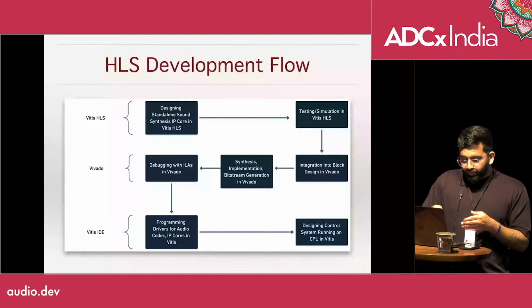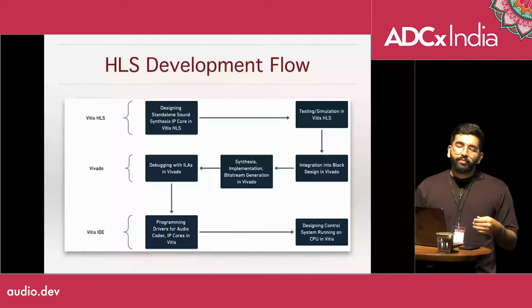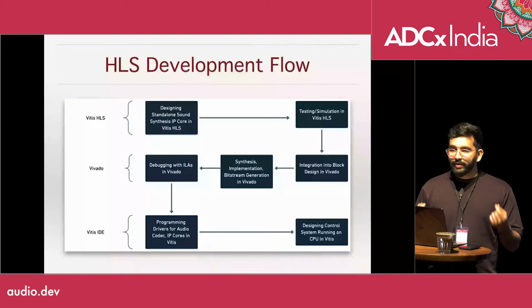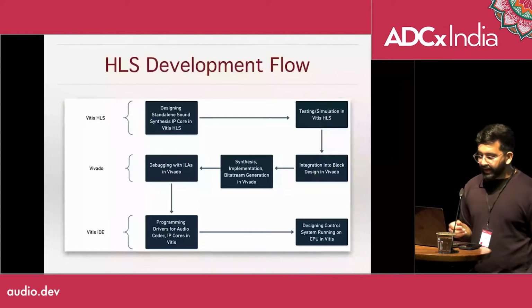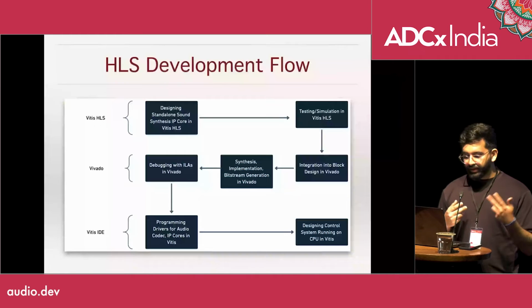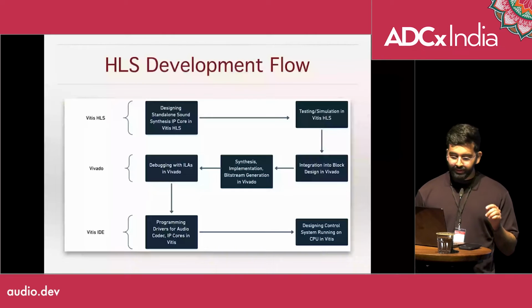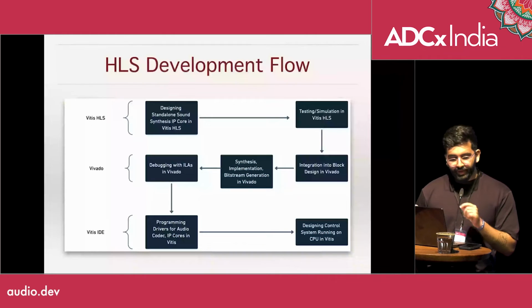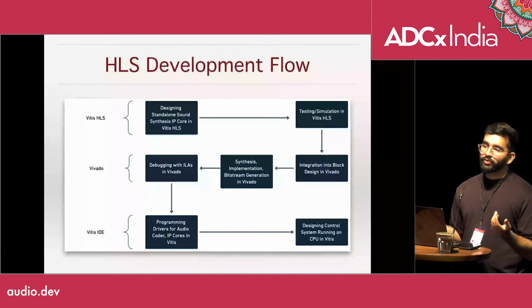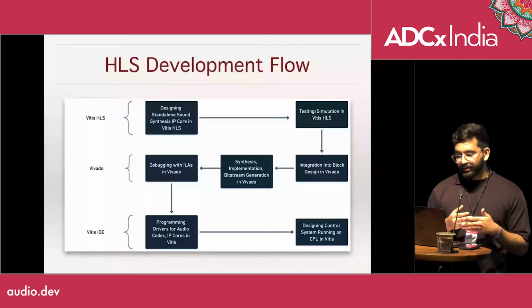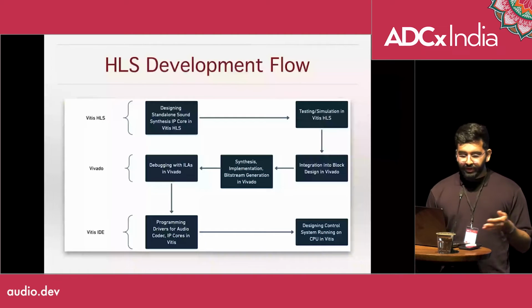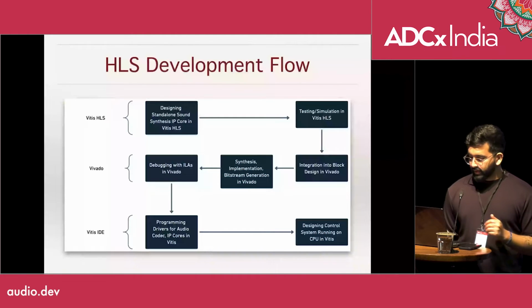And then we move to Vitis IDE, where we program our CPU, which was there on the SoC as well. That's where we make the drivers, we initialize all the hardware that we generated, and make sure all the configuration and initialization is done. After that, on the CPU, you can also design your control system for assigning parameters, launching gates for envelopes, things like that.